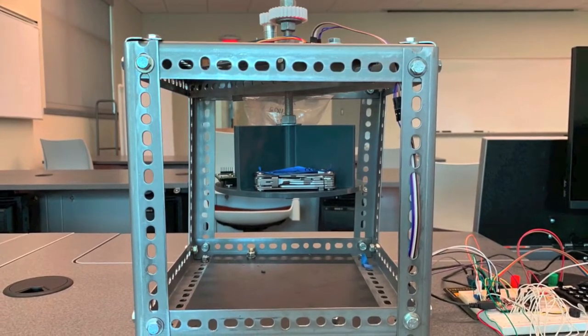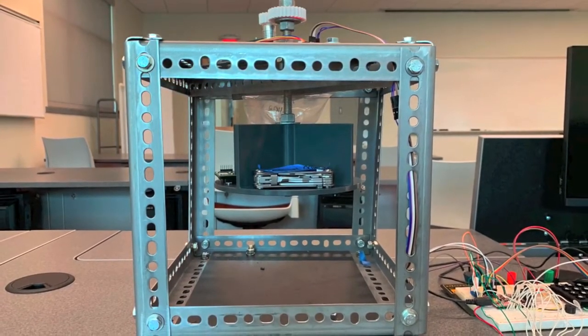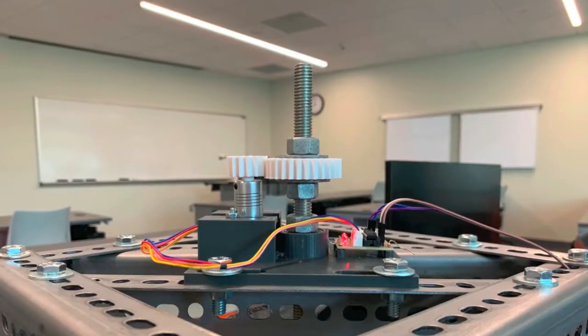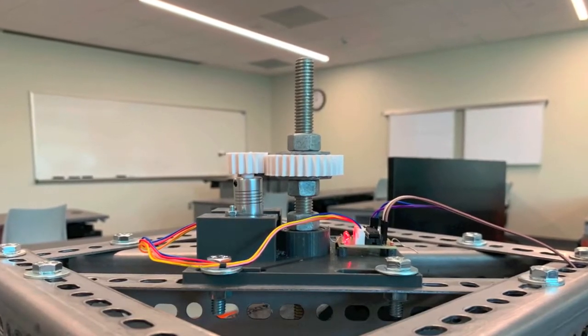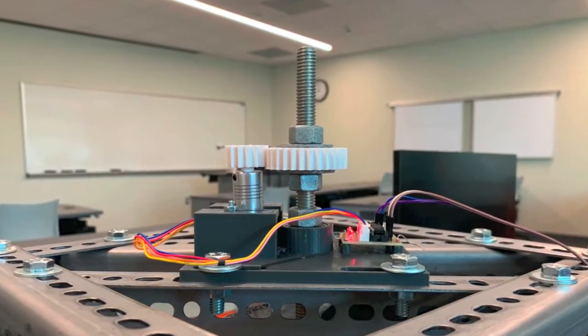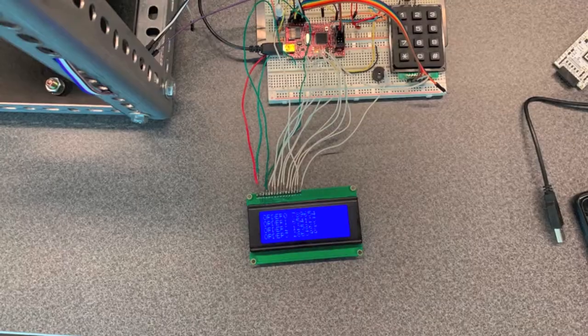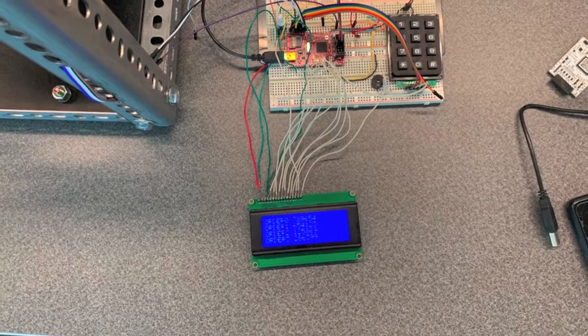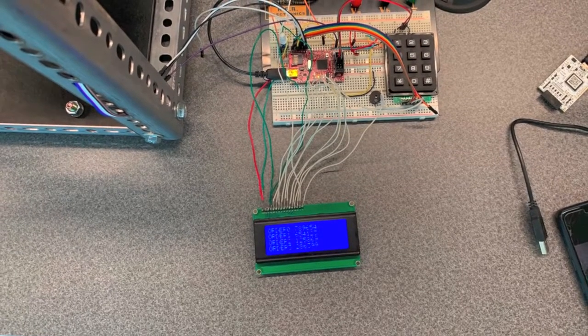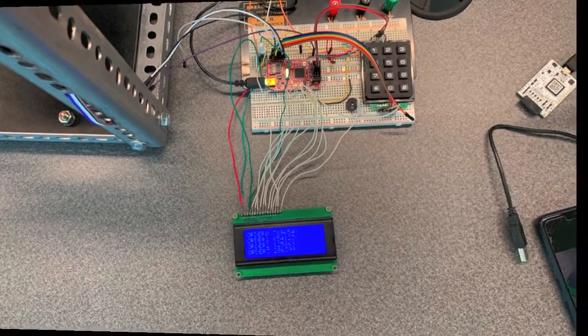We developed the prototype to test our initial dispenser design and to prove concepts that would be present for next semester's design. The prototype is constructed of a metal frame, a 3D printed carousel housing unit, and a 3D printed gear train to allow more torque onto the carousel shaft rotation. A PIC microcontroller is used to read input from a matrix keypad, display characters on an LCD screen, and rotate a stepper motor that connects to the gear train.